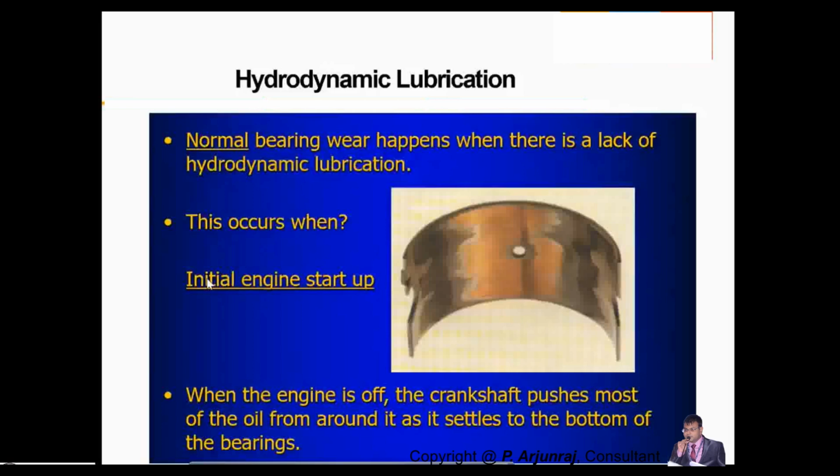When you start the engine, if you do not get the oil to the bearing surface or the lubrication system surface, basically the crankshaft in particular, and even the main oil gallery that I showed in the line diagram, so if you delay the rate of the supply of oil with respect to time, then it may also lead to the failure.